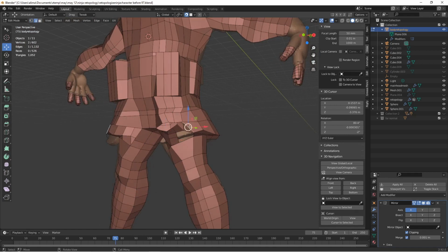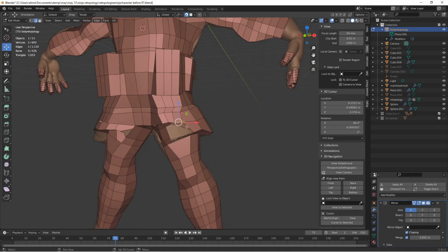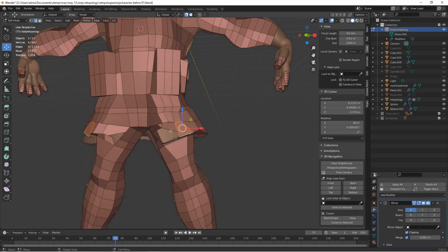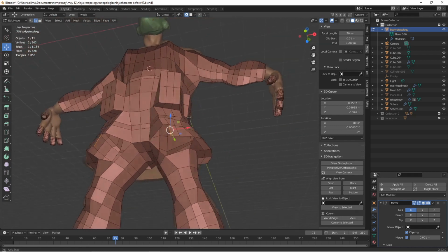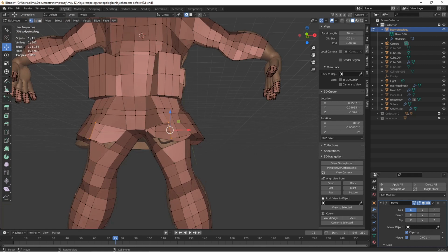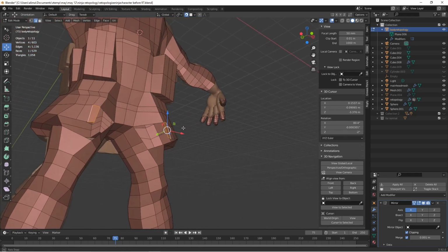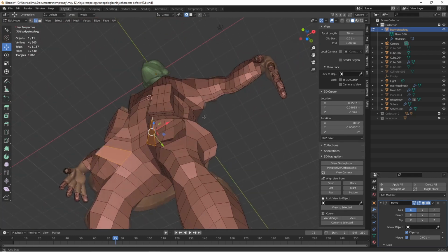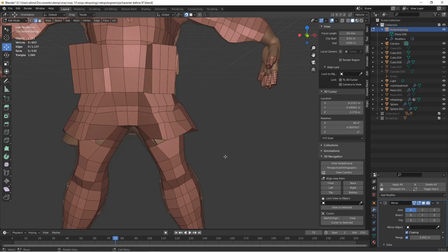Go to Edge Select. I'm gonna select here. Typically, I'll select here, here. Typically, this first edge, it's good to manually select it, and then after that, you can use the F2 add-on. This here, what we can do is go to Vertex Select, select here, hold Control. Then we'll go to Edge Select, select here, or select there. Still holding Shift. So with that, I'll select here, here, as well as here. Then I'll press F to fill. I'll hold Alt, press A to deselect.